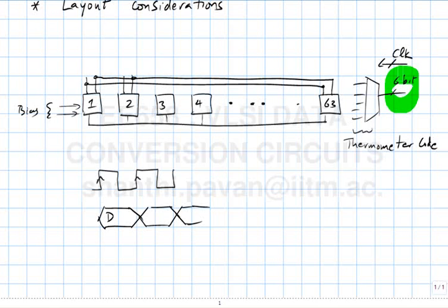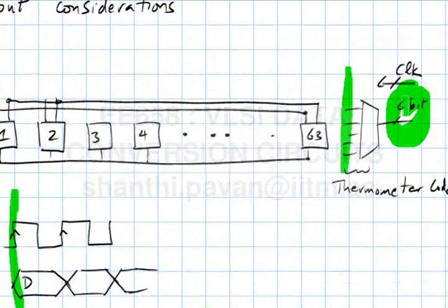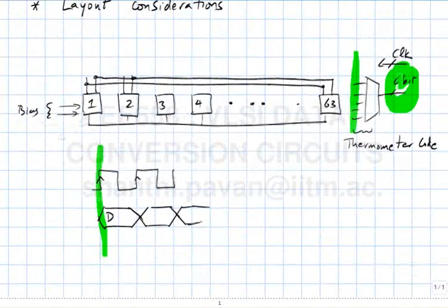So the 6-bit data is all synchronous with the clock, correct? Can you comment on what will happen to the edges of these decoded outputs when you pass through a decoder? You're taking this 6-bit digital word, and you're generating 63 lines through some combinational logic. If I look at the transitions, ideally if all gates inside the decoder were delayless, then as soon as the data changes, the outputs must all change instantaneously. In other words, the delay is 0.